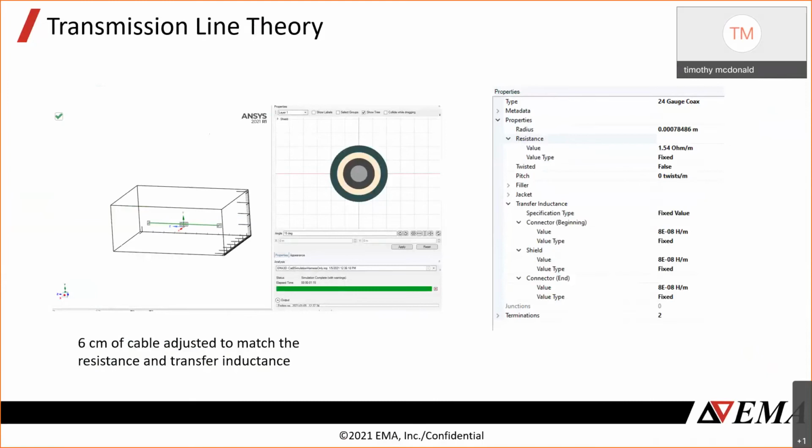So as you can see, a lot of things in the workflow are set up that way, where we can zoom in with more fidelity when we need it. When we want to zoom out a little bit, we're able to use transfer impedance of cable shields, seam impedance characterization, and other types of shortcut modeling tools that retain the accuracy but allow us to specify them in seconds. So we have multiple ways to handle the effects of that connector.